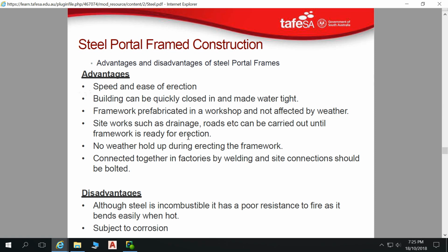When you're doing your portal frame construction, if you're going to be building through winter time, yes, it's good to get a good compacted hard base happening first, or even your slab happening first if you can. But at least a good compacted hard stand area to go under your base first before doing your portal frame construction. But just because of the machinery that you're going to be using on that site there, telehandlers and cranes and scissor lifts, etc. You don't want like a boggy, muddy site.